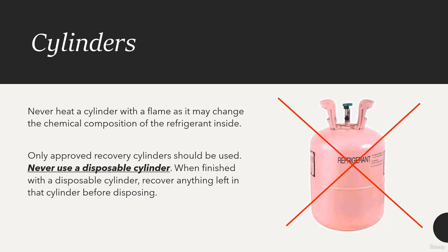Never use a disposable cylinder. Whenever you have a disposable refrigerant cylinder, such as an R410 or an R22 cylinder, when you're finished with it, that cylinder should be recovered down to 0 psi and disposed of properly. Never refill those types of cylinders as a recovery tank.